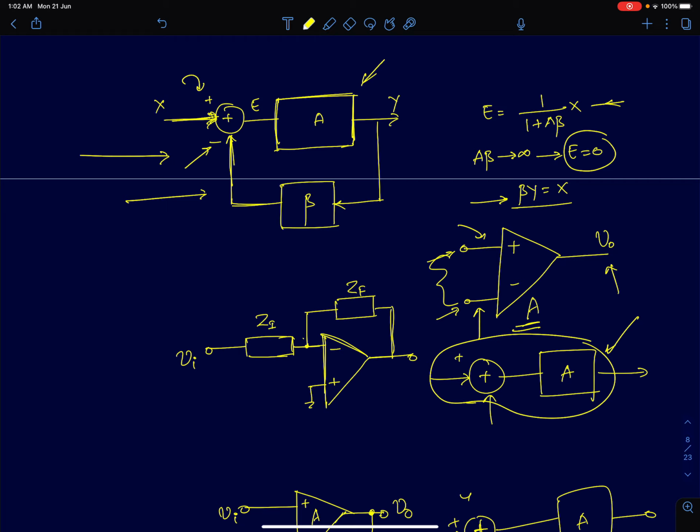If you know that the circuit has negative feedback, then all you need to do to analyze this Opamp circuit is just equate the positive and negative voltages. You should just equate the two voltages, or the difference between the two voltages will be 0.